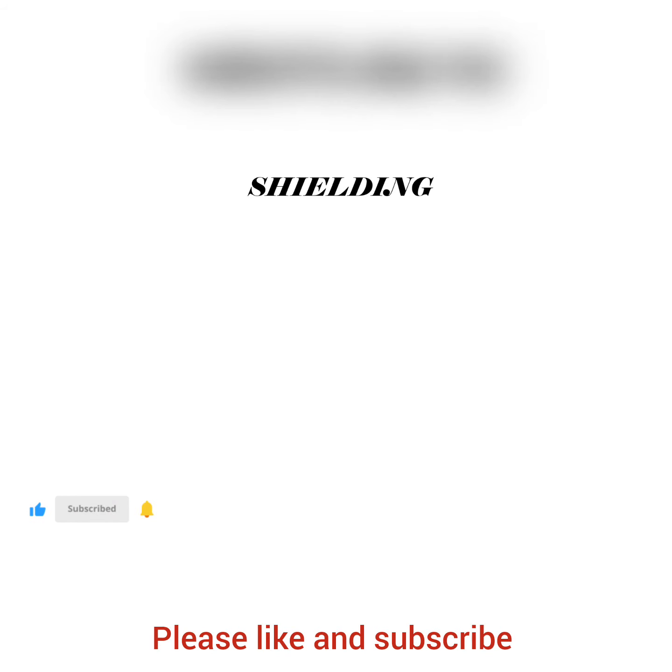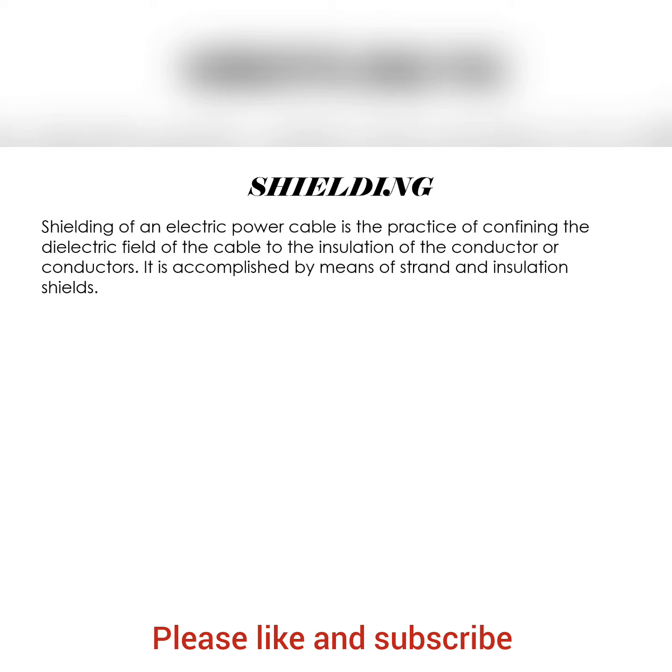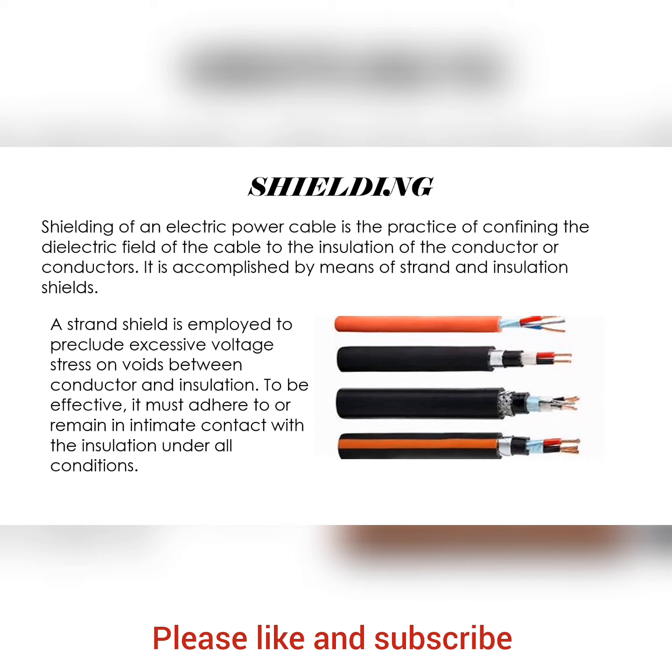Shielding of an electrical power cable is a practice of confining the dielectric field of the cable to the insulation of the conductor or conductors. It is accomplished by means of strand and insulation shields. As you can see in the different kinds of cables, the strand shield is employed to preclude excessive voltage stress on voids between conductor and insulation. To be effective, it must remain in intimate contact with the insulation under all conditions.